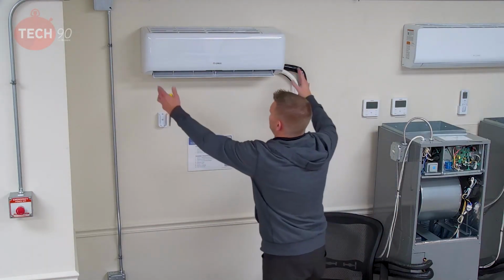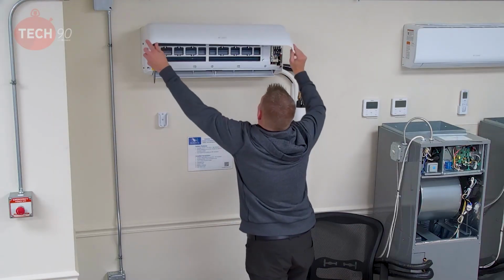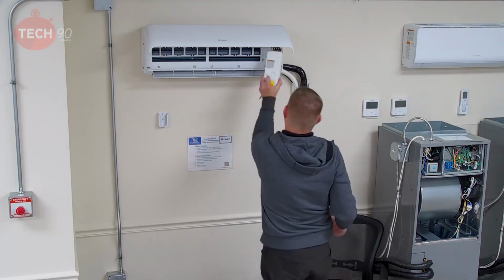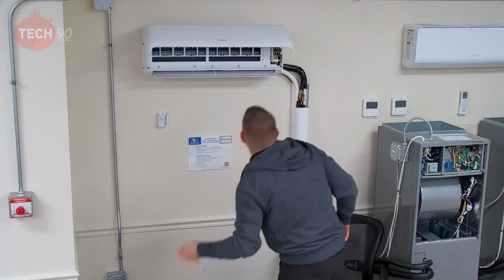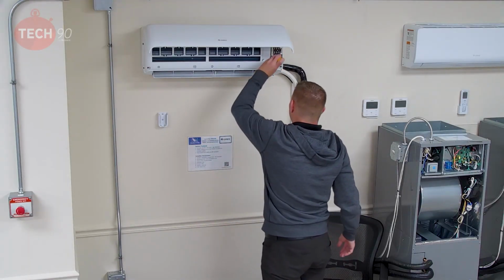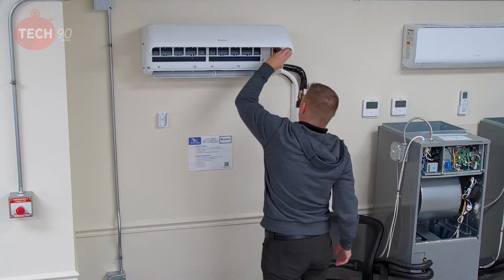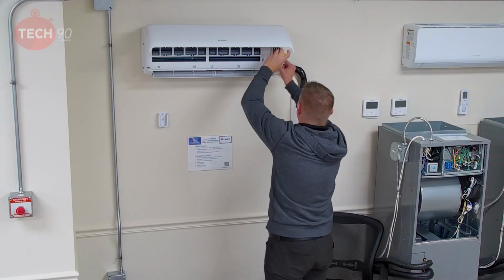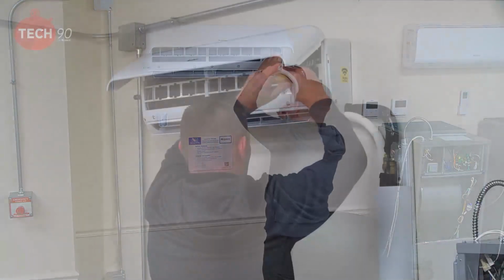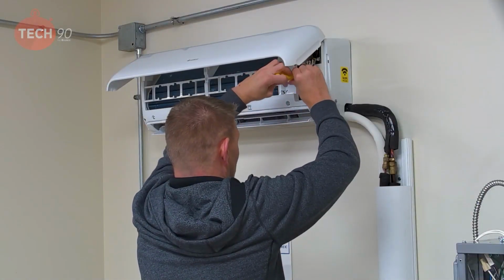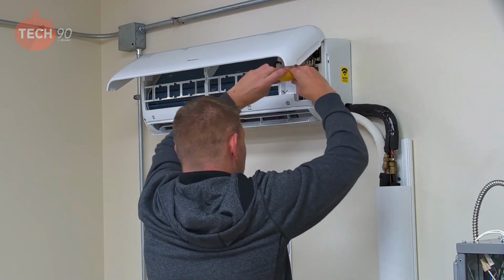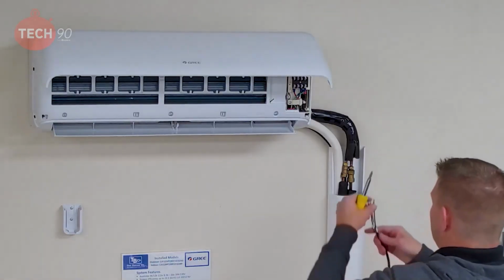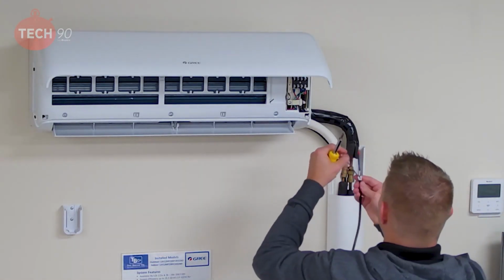So what we're going to do first is lift this cover up. Did you know you'd have to take this cover off right here? Already took that cover off. Power is off. What we're going to do is disconnect number 2 from the outdoor unit here. Then we're going to hook up all 3 connections to the indoor. Again, they're labeled 1, 2, and 3, just like the outdoor. So you hook up 1 to 1, 2 to 2, and 3 to 3.